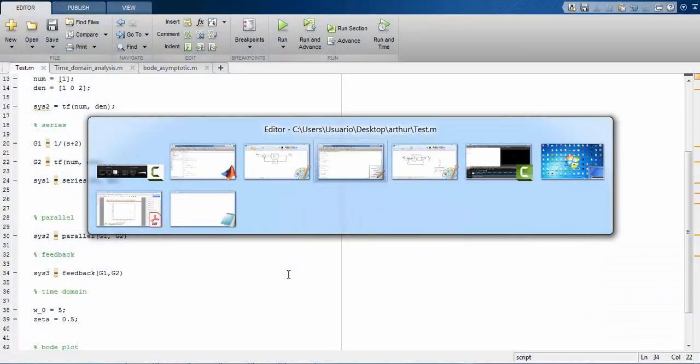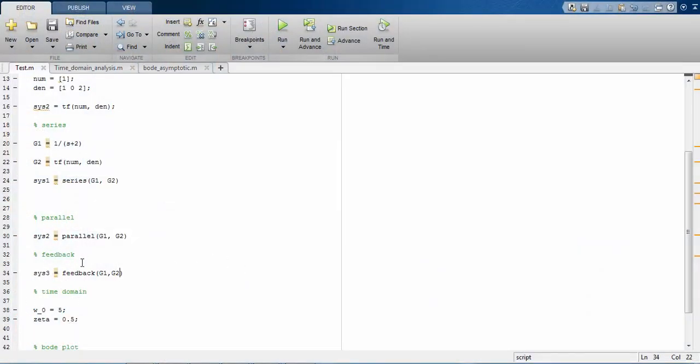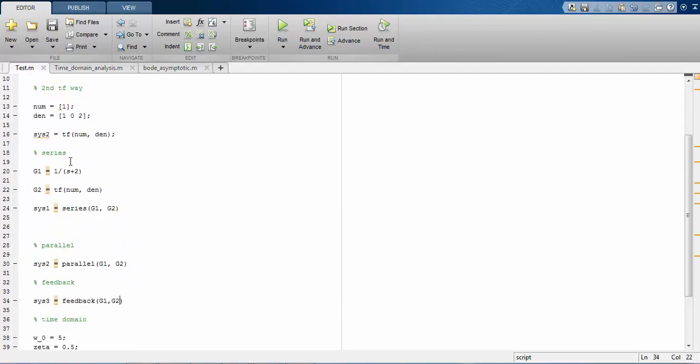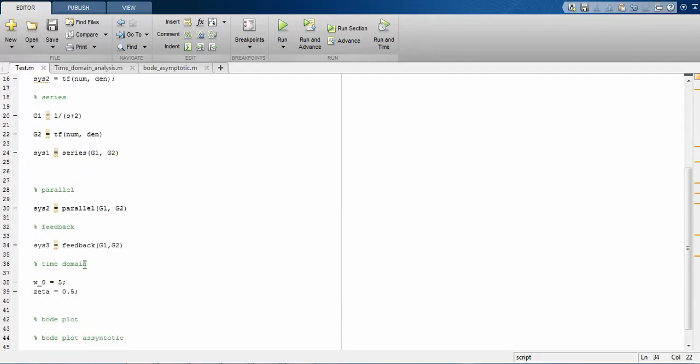Okay, besides that, this is a very nice beginning. We can write our transfer functions, and associate them in series, parallel, feedback, and everything you want. And MATLAB has some commands with which we can easily see the output of the system. For example, if you use the step command, it will give the step response of the system. So for example, the step response of G2.